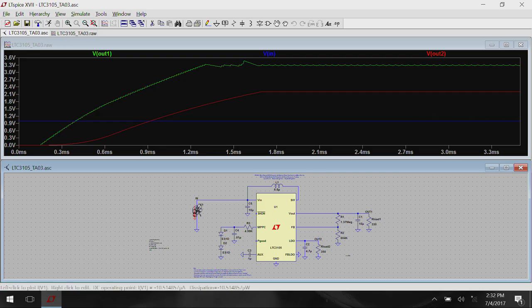As you are harvesting the energy here, let me close this. Okay, and actually we should keep this together, only then you will appreciate this. This is the solar panel. Once you connect equivalent of a solar panel, I have just connected a voltage source now, you will get 2.2 straight away, that is this line. This 2.2 you can take and power the microcontroller, start running the microcontroller, acquire the temperature of the bearing, ball bearing, and store that value.